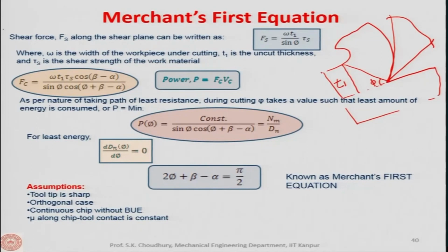This is the width of the workpiece, so let us say this is the width of cut W. So, W into T1 by sin phi, which is this length T1 by sin phi, this will be the area, and this is the stress.